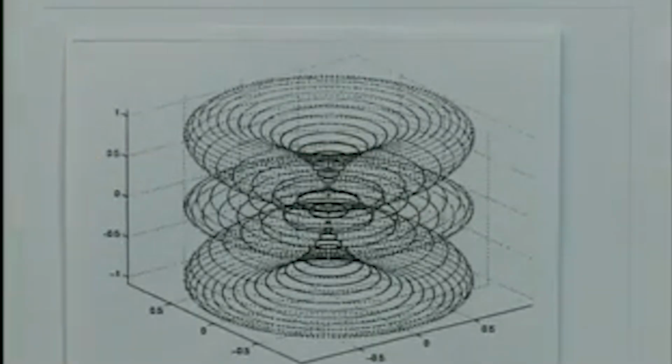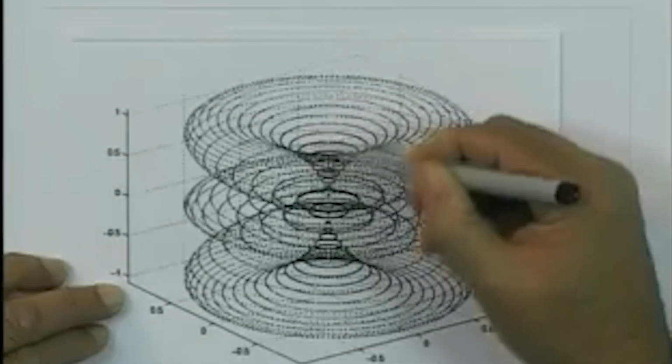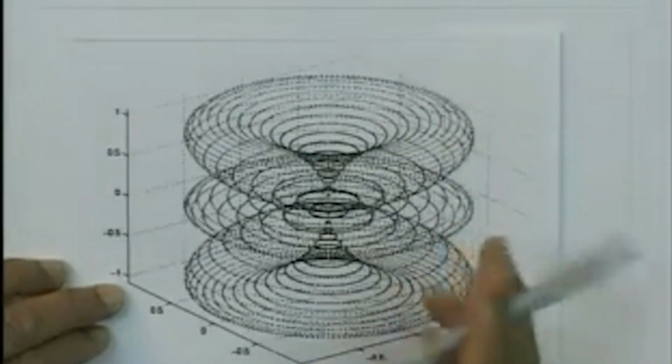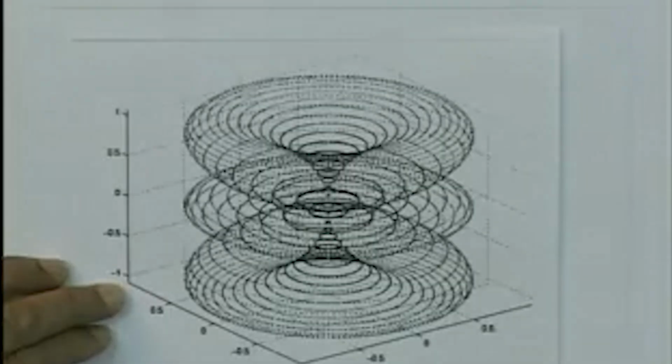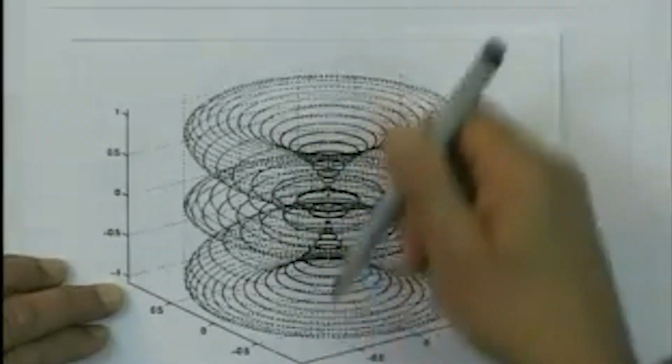So this corresponds to h equal to 3 lambda by 4. You see here this is the direction of null which we have shown, and this is another direction of null. In all these directions there is no radiation. There is a direction here which is maximum, a direction of null here again, and a null which is going downwards.